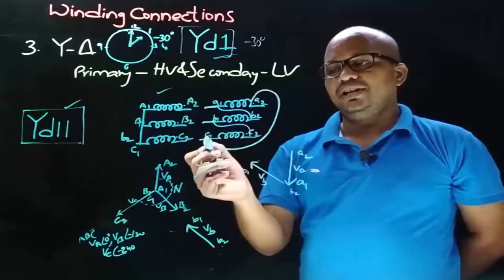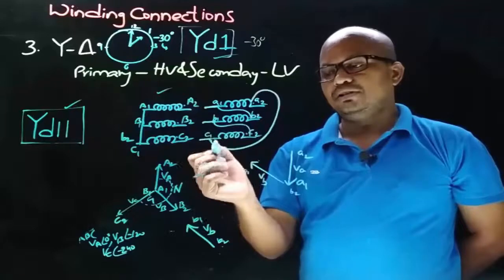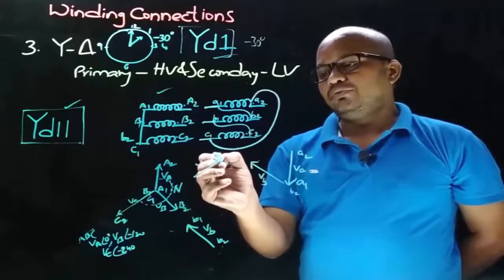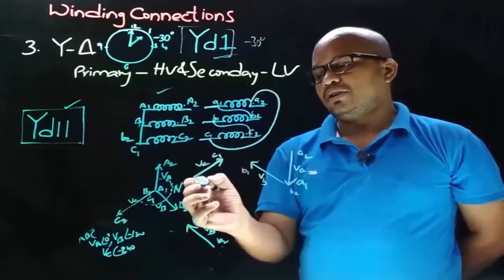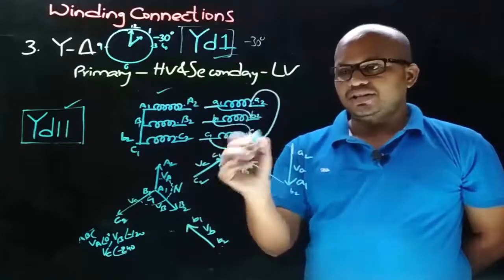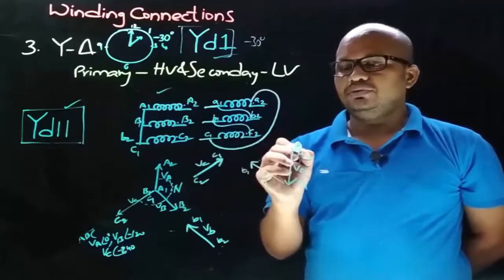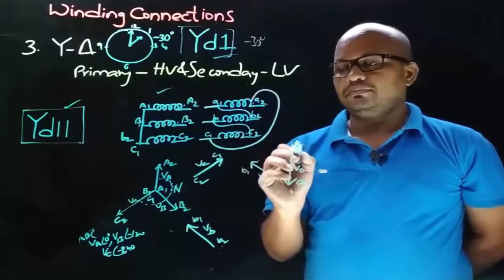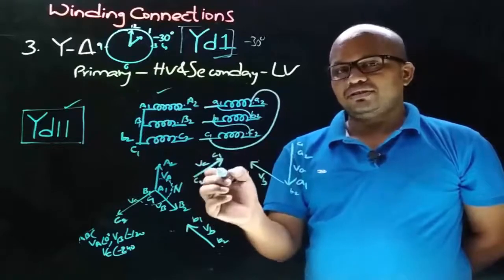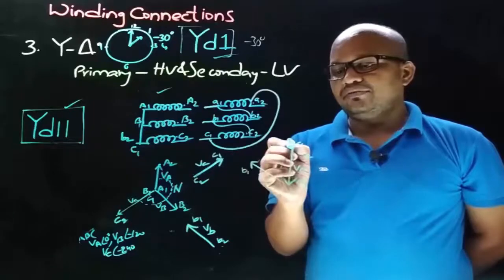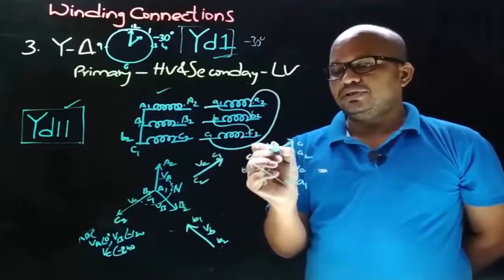On secondary side the winding connections are taken from non-dot end, means arrow will point towards the connection we took from, that is C1. So other end will be C2. And observe in winding connection that A2 is having C1 connection, means here to A2 there will be C1 also. So as we got the VC phasor like this, move this phasor such that it is having C1 like this. So this is VC phasor.